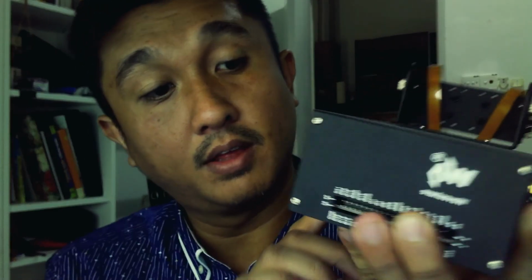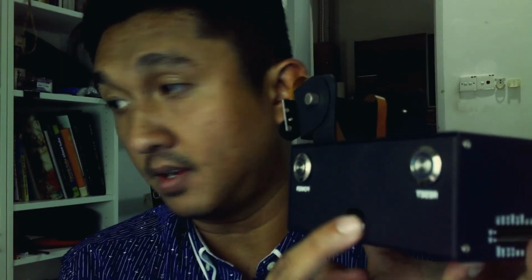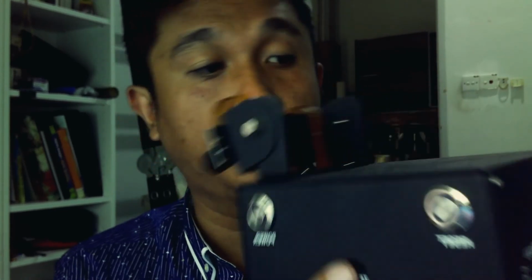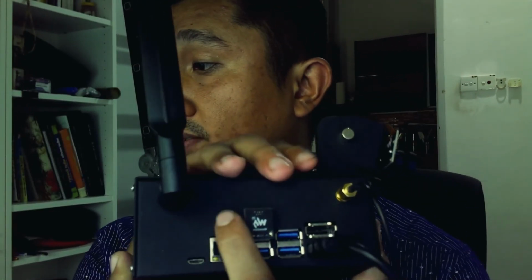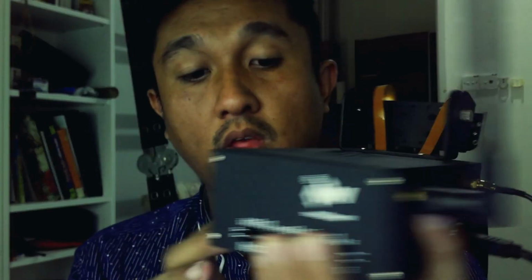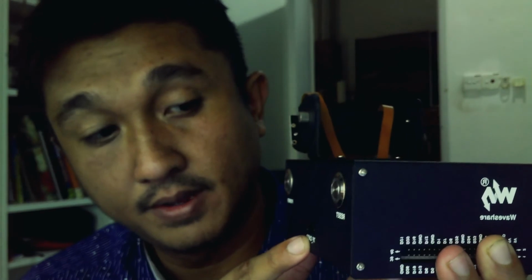Yeah, so in front of this Jetson Nano, there is a slot for you to put in your memory card. Basically, if you look here, this is all the USB part, the USB and the connectivity that you can put into your Jetson Nano. So the memory card slot is actually at the back of those USB, the other side of the Jetson Nano. So you just put your memory card inside.